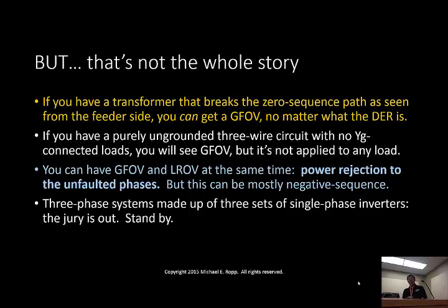But part of the thing that we can run into, and we've actually seen a few cases of this recently, is if I have three single-phase inverters, I form the island, whether it's faulted or not, those single-phase inverters, generally speaking, are not talking to each other in terms of maintaining 120-degree separation between the phases. So they may collapse. They may do something like this. If they do that, now I can get negative and zero sequence currents. I've actually got a negative and zero sequence source on the PV side. So depending on what my negative and zero sequence circuit impedances are, we can get voltages from there.